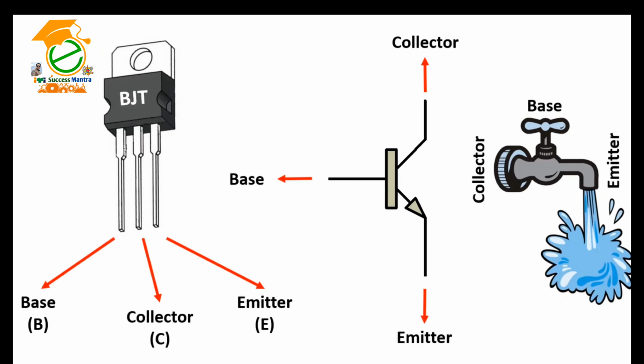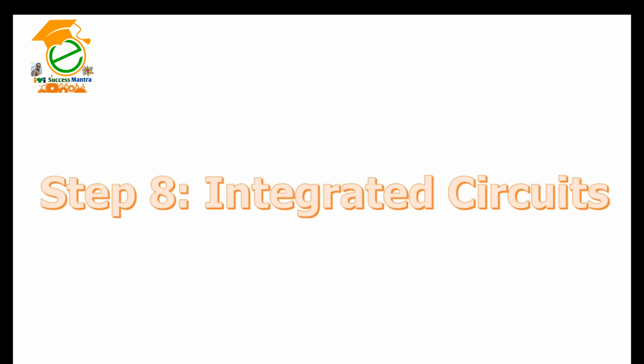Transistors have their part numbers printed on them, and you can look up their datasheets online to learn about their pin layouts and their specific properties. Be sure to take note of the transistor's voltage and current rating as well.